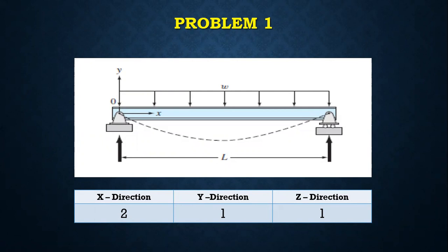The software initially will ask how many grid lines are required along the x direction, y direction and z direction. As we know, in any software, you should always be able to identify the global axis, that is, which one is up. That is most important. Here in SAP 2000, the vertical is the Z direction.